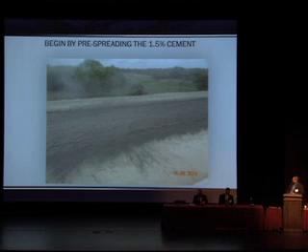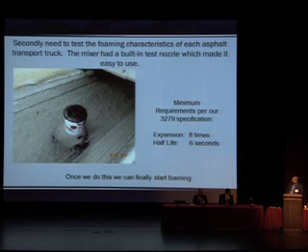So we begin by spreading out our cement. Like I said, we were at 1.5% cement. We spread that out on the existing base. We then got our asphalt truck in place, and we tested the foaming characteristics as per the spec. We used this incredibly technical piece of equipment here to test our expansion rate and our 6-second decay. Lucky for us, the equipment we were using was a Wirtgen mixer, and it had a special nozzle that allowed you to do it pretty easily.